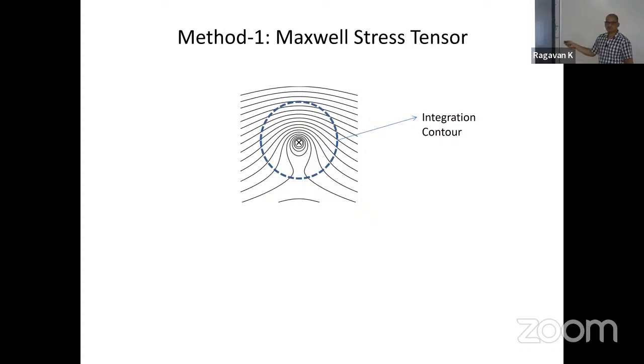Any questions on the earlier slide? Okay. So the stress calculation, the force calculation, you are doing from the magnetic field as well as the current-carrying conductors, the two MMF sources present in the machine. Calculating the stress and utilizing the area, we can go to force. So the question is, what is the difference between the MMF based method and the stress based method?